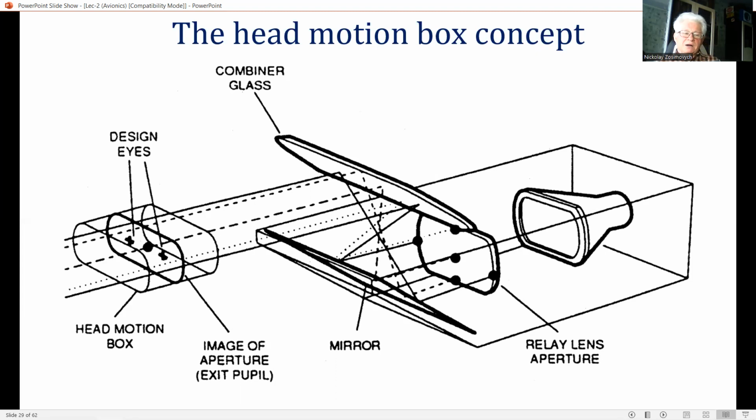The combiner comprises a parallel plate sandwich of planar convex and planar concave glass plates with a holographic coating on the spherical interface between them. The holographic coating is formed on the spherical surface of the planar convex glass plate, and the concave surface glass forms a cover plate, so that the holographic coating can be hermetically sealed within the combiner.